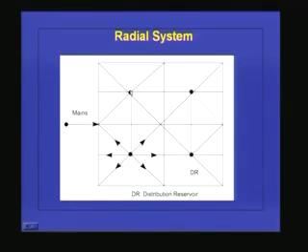So this main will primarily be supplying water to the distribution reservoirs, and from each distribution reservoir the water will flow along pipes laid out in a radial fashion in that particular area where you are supplying the water. Like this here I have shown. Similarly, this one will supply to this particular area. Because these distribution reservoirs can be elevated reservoirs, I will be able to maintain the pressures much more uniformly in a radial system.